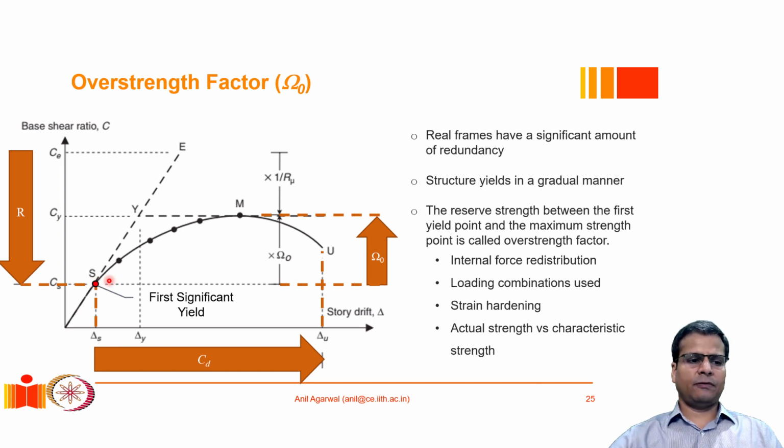And then in the previous example, we had assumed that the response is like this, like a straight line. But that was okay for a linearly elastic, perfectly plastic type of model. But most structural systems have quite a bit of strain hardening. This strain hardening could be material level strain hardening. It could be because of the moment curvature curve, even for elastic plastic material properties. The moment curvature curve itself has some level of gradual increase in the moment until the entire cross section plasticizes.